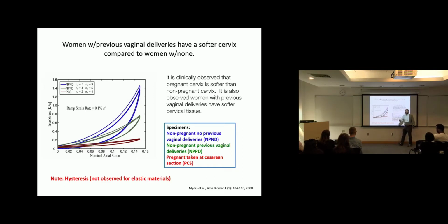Okay. In poroelasticity too, there will be, because the water came in. To flow the water in, you do some work. When it goes out, you do some other work. And there is dissipation in this whole process because diffusion is viscosity. So you're going to dissipate water energy. So both these processes will dissipate energy. Okay, I'll come to which is what in a second.